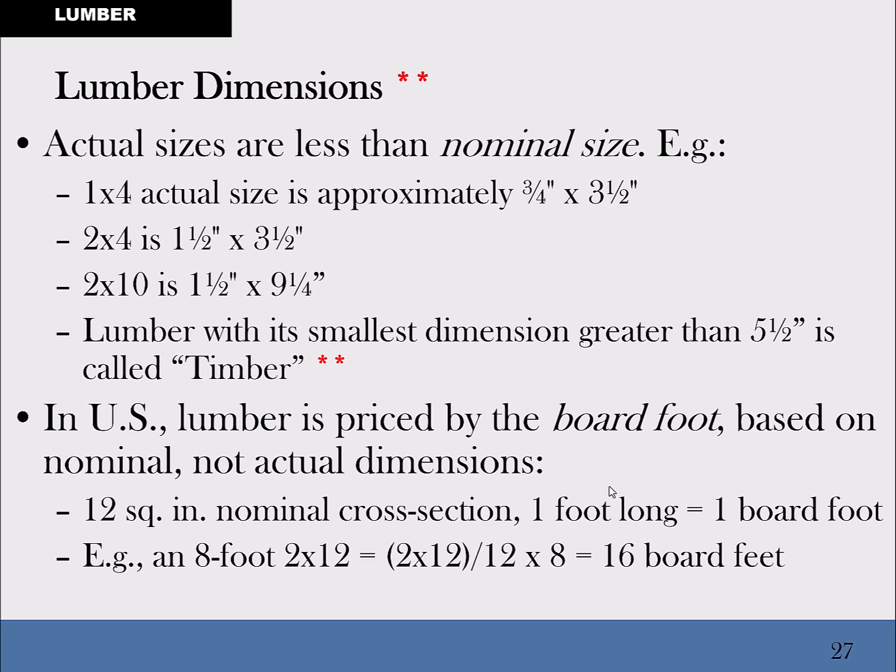Now, in a very simple way of describing what a board foot of material is, if you had a 1 foot by 1 foot board that was 1 inch thick, a 12-inch by 12-inch board that is 1 inch thick, then we consider that a board foot. So generally, up to 1 inch of thickness, everything gets rounded up to the whole number.